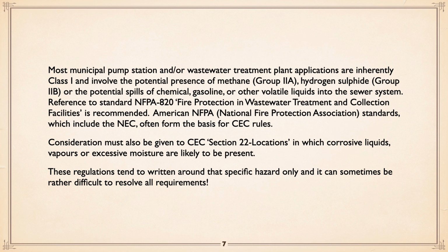What that is really saying is not only should you worry about the issue of explosive vapors and whatever, but also corrosive liquids and vapors. These regulations tend to be written around that specific hazard only, and it's sometimes rather difficult to resolve all requirements. In other words, you have to, in some cases, meet hazardous location requirements from an explosive point of view, along with corrosive vapors and all that good stuff.